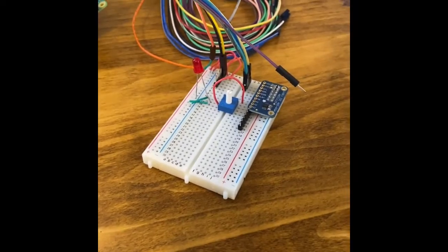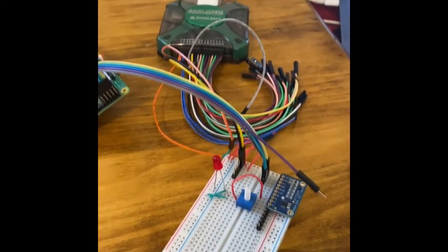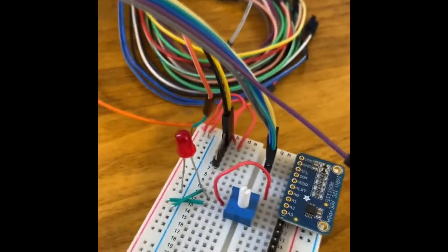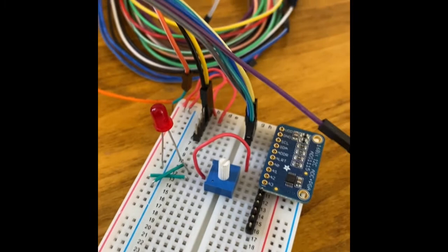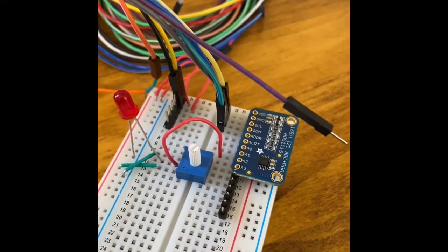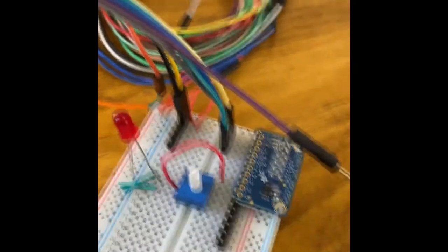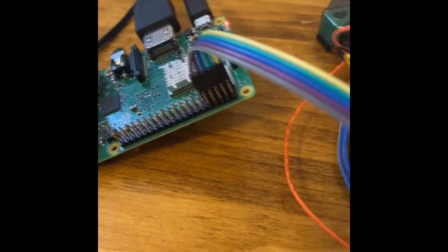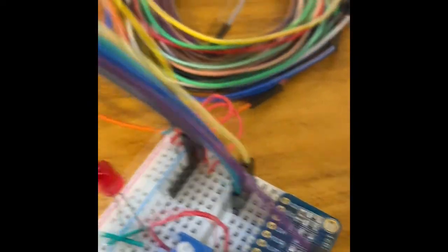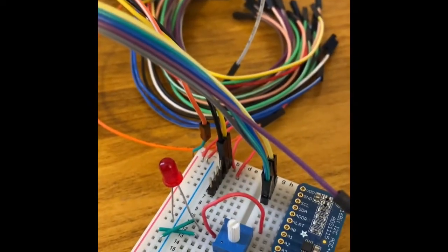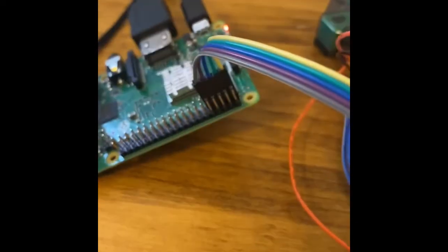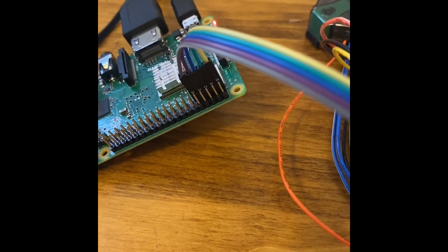Starting on the circuit board, an AC voltage is fed from the Analog Discovery 2 at these pins here. From there, a potentiometer can change that RMS voltage and feed it into the A1 input pin of the ADC chip. The Raspberry Pi 3 can feed in the VDD and ground for the ADC chip, which is at 3.3 volts. The SCL and SDA output of the ADC chip is also fed into the appropriate pins of the Raspberry Pi.